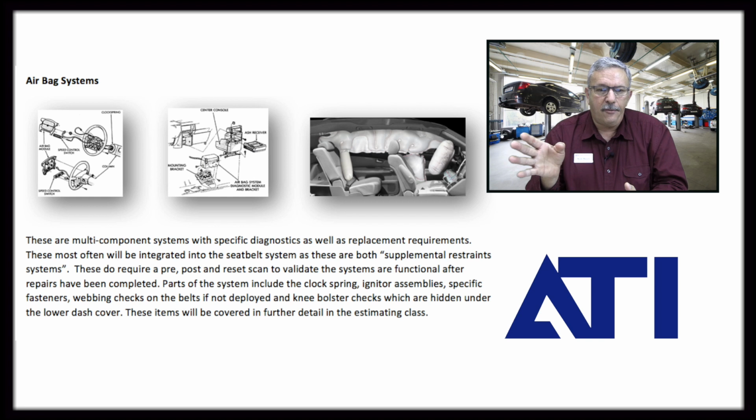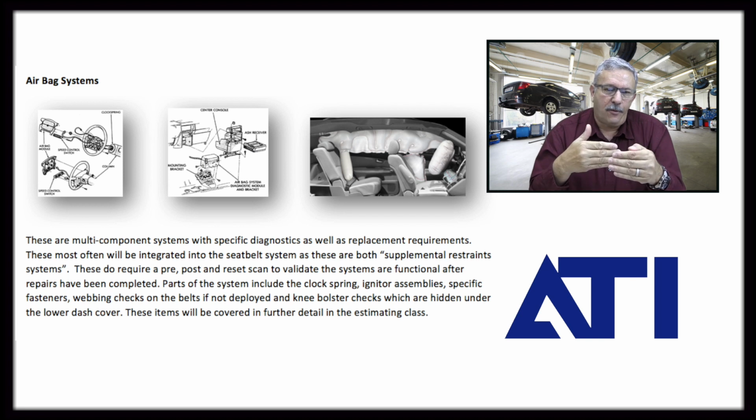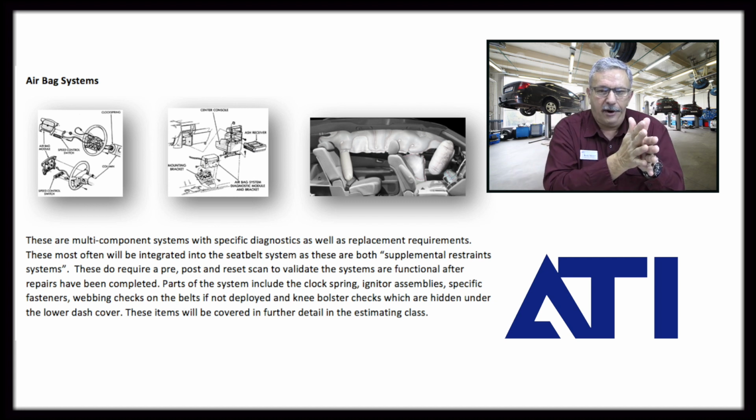They've changed it now, but up through 2015, things like the interior, the A and B pillar interior components that snapped on, all it is a covering, they were one-time use parts. And so it was very specific when we did our estimating processes that it identified it as a one-time only part. And what would happen is, if you tried to fit that part up again, it would feel kind of loose. It's really important that it's tight.